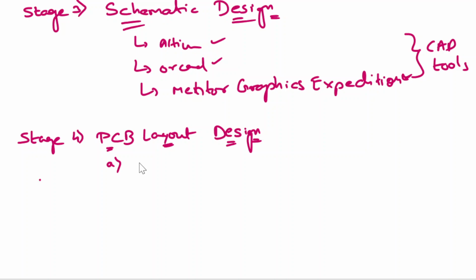In high-speed designs and trace width, why do we have to go to the PCB fabricator? Because, as you are saying, the length and width of the traces may need to be very minimal or maximal, so that they are able to fabricate such a PCB. That's the reason we are checking with the PCB fabricator.